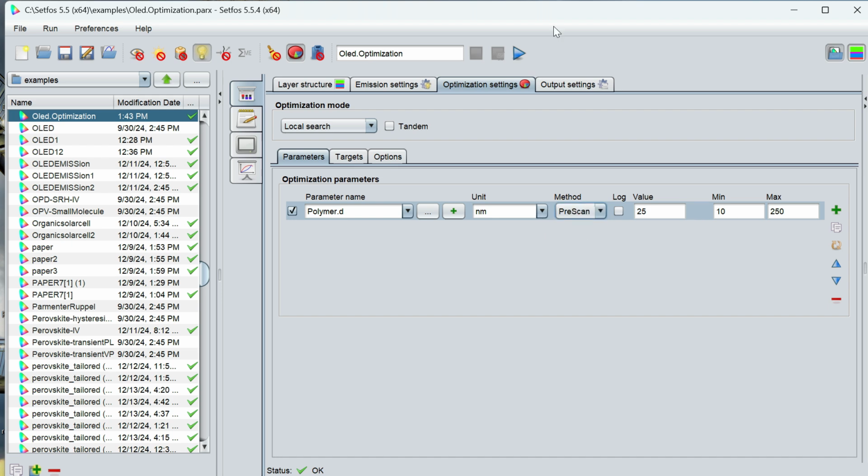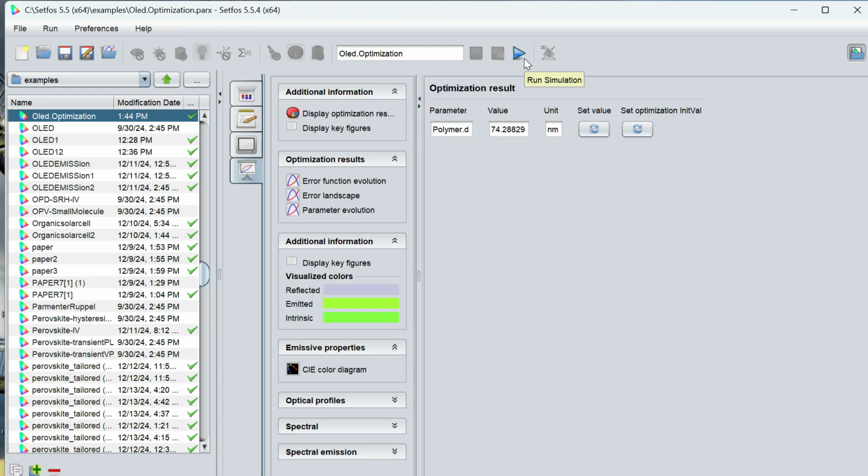If you select the pre-scan method, you can see the value. Pre-scan generally means it will calculate the lowest error value. In this value you can get the idea. If you change the thickness of the layer, the radiation penetration continuously decreases at the entry of the layer, because absorption and scatter possibilities continuously increase.